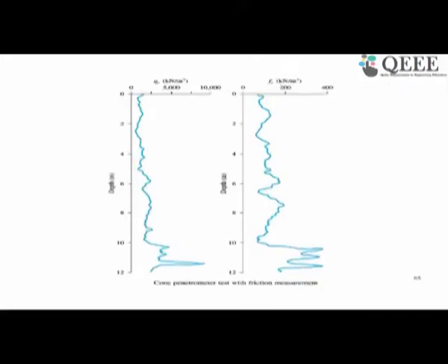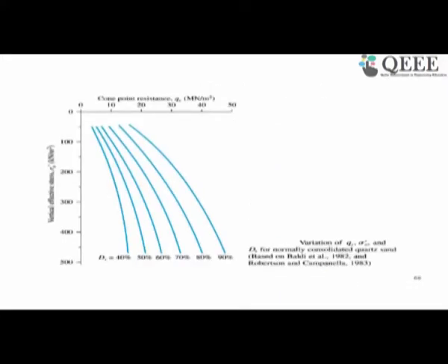Another typical characteristic of the data recorded from a CPT, as you can see here, is that corresponding to different depths you have QC values. Similarly, the friction component also corresponds to different depths, which are given here. Now, the vertical effective stress with the cone point resistance can also be found for different relative densities, for 40%, 50%, 60% and 90% relative density.